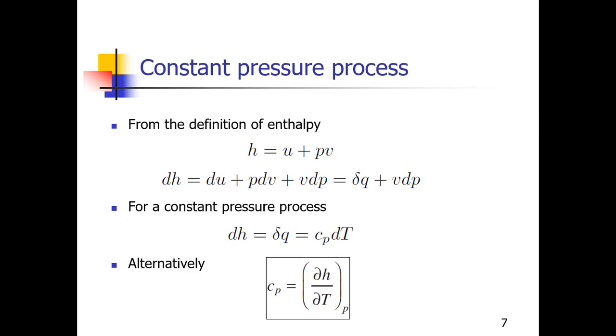Okay, let's go to the definition of enthalpy. Specific enthalpy, I should write specific here. Specific enthalpy is equal to specific internal energy plus pressure times specific volume. Okay, so when we take the differential on both sides, it becomes dh equals du plus P dv plus v dP.